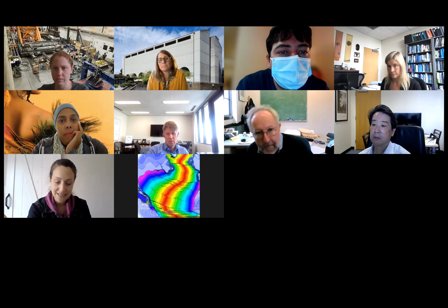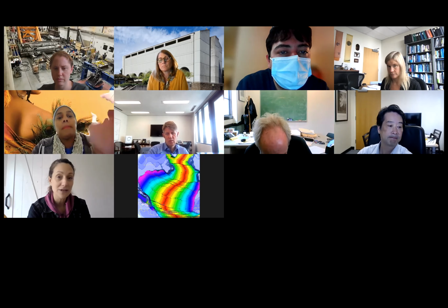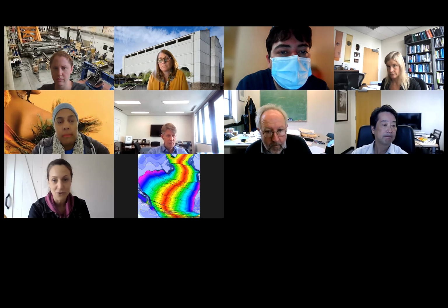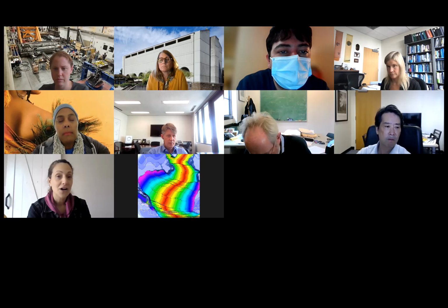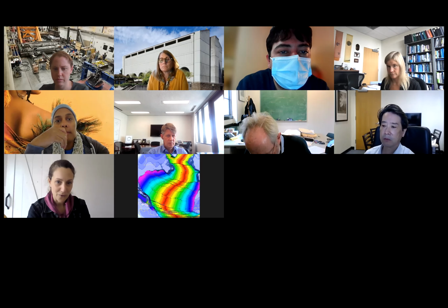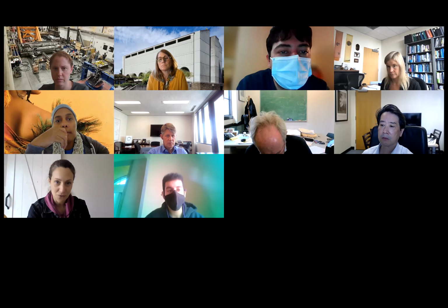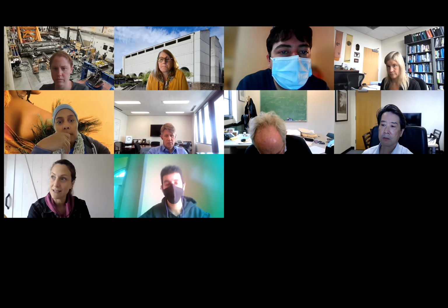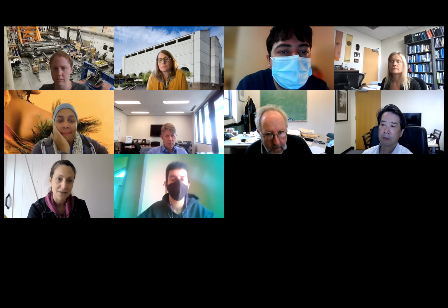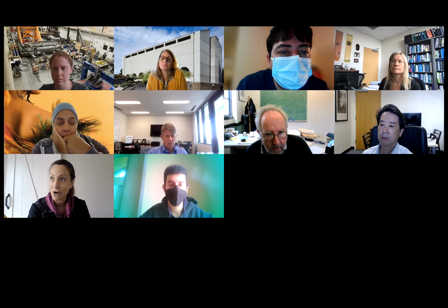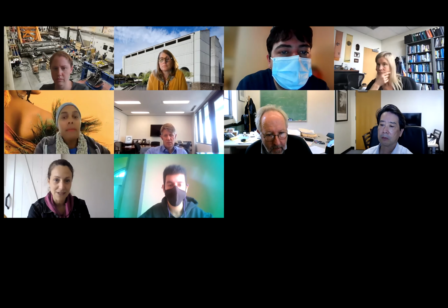What happened basically is that this building was being built in an area that has supported similar buildings in the past, with similar ground conditions and similar foundation styles. And so there was higher confidence from the engineers in moving forward with some of the traditionally used approaches and techniques, and not extremely thorough soil investigation and soil testing, because we could depend on some of the information from neighboring structures.